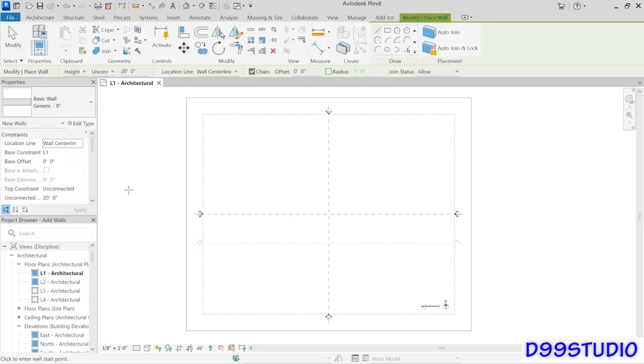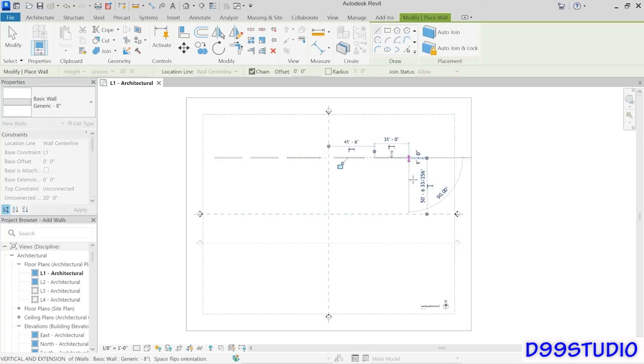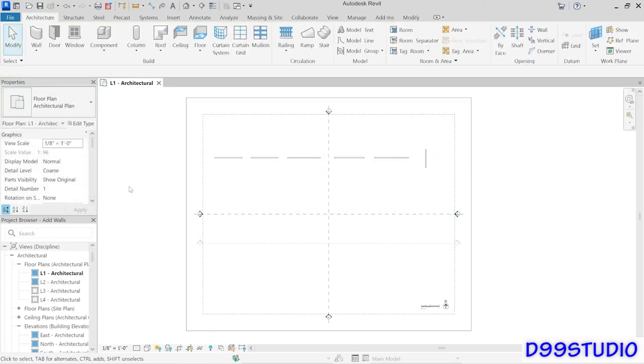And now what I want to do is draw some walls that are just simple straight lines. So I'm going to draw one here that is maybe about 25 feet long in imperial. If this is metric, then that's going to be about 6,000, 7,000 millimeters, somewhere in that range. And then press escape once and then draw it again from here to here, escape once, from here to here. And let's continue that and create 5 separate walls here. And then let's draw one more over here that's in the opposite direction. And then let's click the modify tool to get out of there.